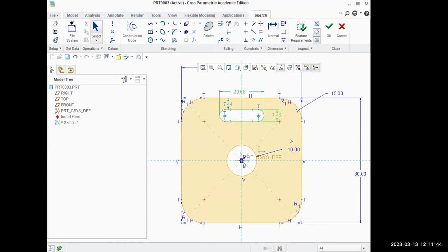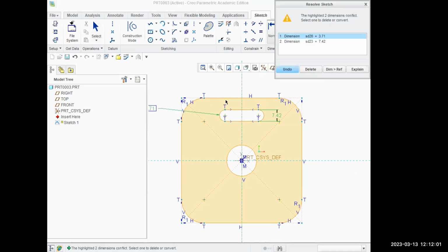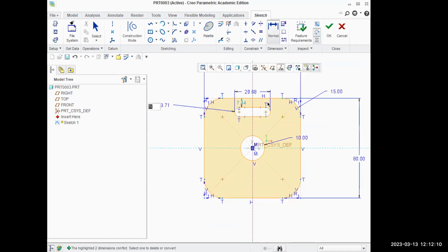Do you want me to repeat? Right. So what we have to do is, with respect to the given job, whatever the referred dimensions are there, you try to place those. Now here the radius is mentioned. Now you try to drop the radius here, but it is saying some dimension already exists. Diameter is given. So I am deleting that diameter now. Just delete that. Now next one.